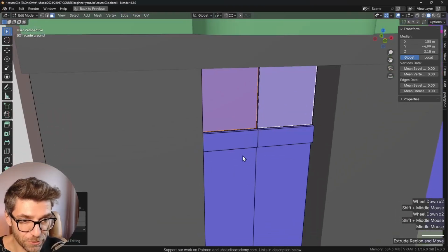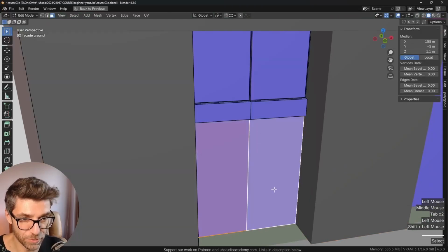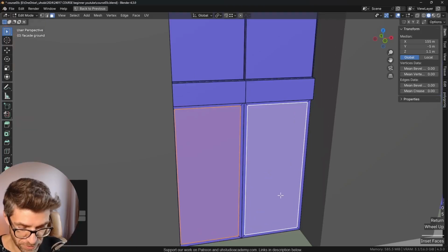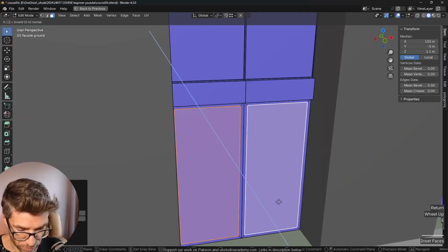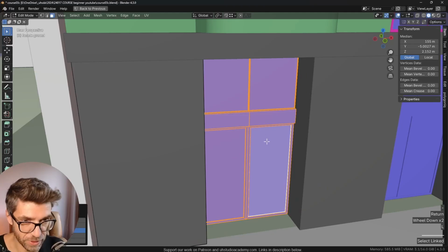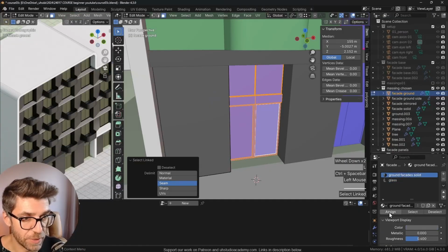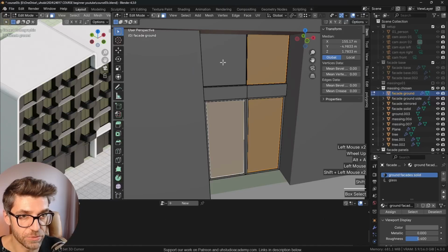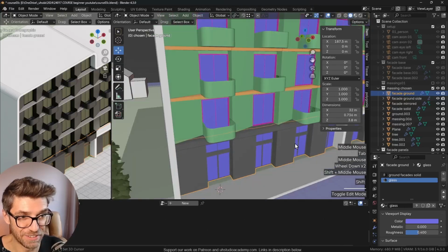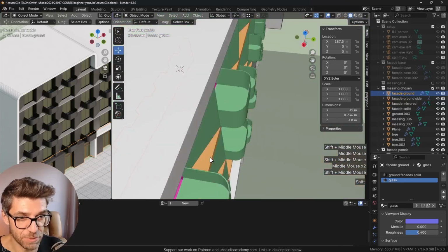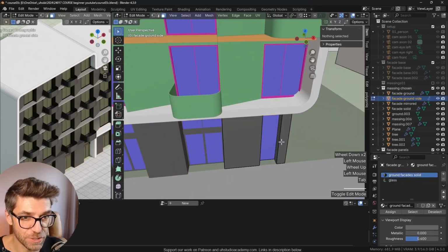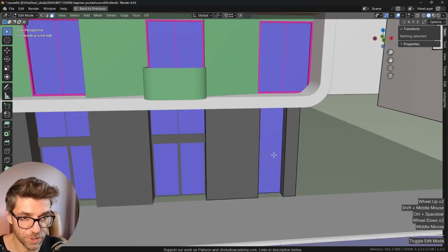And on the bottom though, because these are going to be operable walls, we need a thicker frame. So 0.05 and extrude 0.02 in the negative. Okay, so select everything. We're going to make this the same area, and I'm just going to grab the glass and make the glass glassy, if that makes sense. And as you can see, because of the way that we're dealing with this, everything transferred itself over except this last one, which let's redo really quickly.